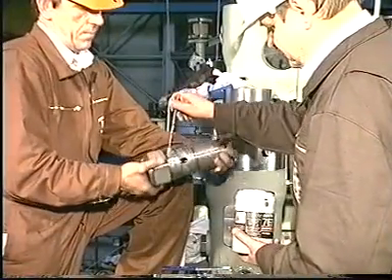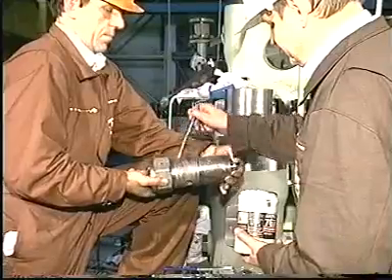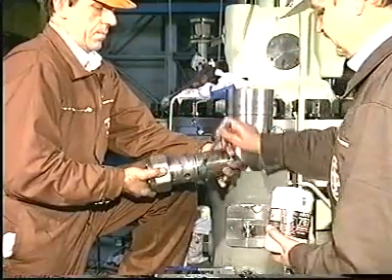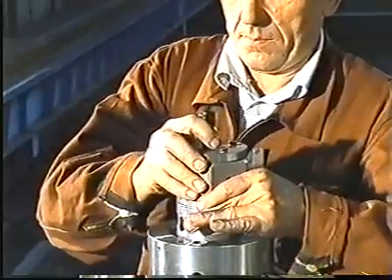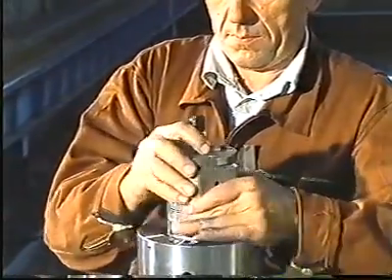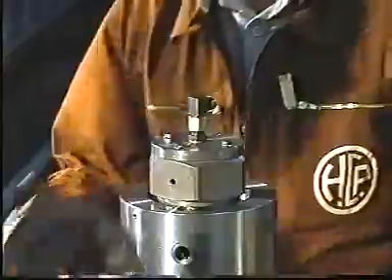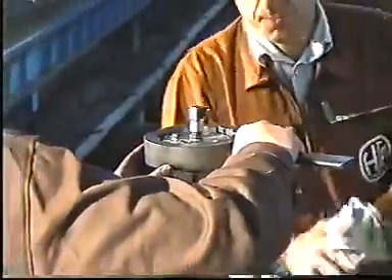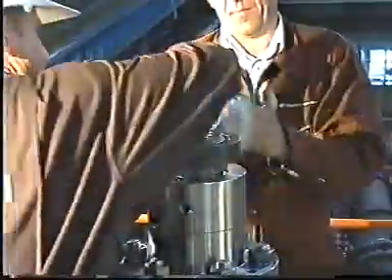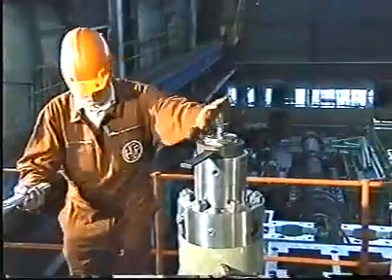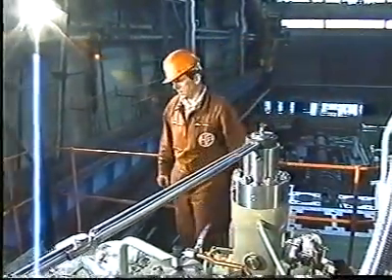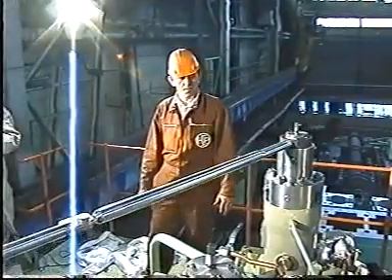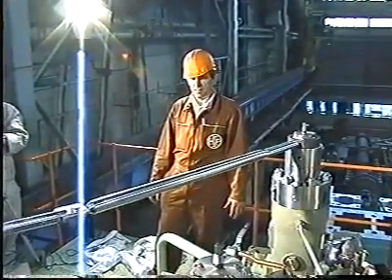Provide the puncture valve with new sealing rings and lubricate with molybdenum disulfide. Tighten the puncture valve to the torque stated in the instruction book, Volume 2, Chapter 909, and mount the plug screws, cover and control air pipe.